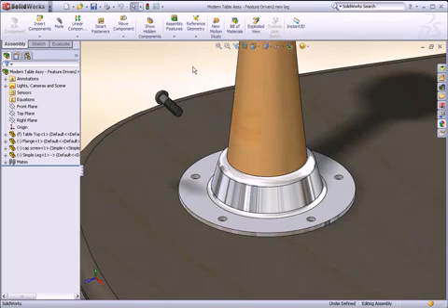Lots of SolidWorks users take advantage of linear and circular patterns when creating things like mounting holes around parts. When it comes time to create the assembly, wouldn't it be nice to have SolidWorks add fasteners to the mounting holes automatically? This is possible with something called feature-driven patterns. Essentially, SolidWorks reuses the pattern feature in the component to place items within the assembly.